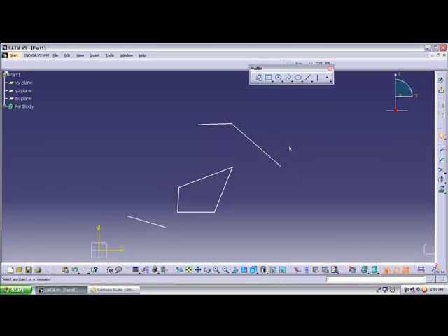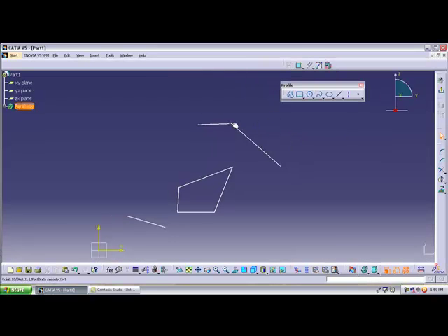So to highlight that icon, we should compulsorily select the profile. Okay, what constraints can you apply for this one? Suppose the line should compulsorily be horizontal, meaning it's parallel to the horizontal axis. Okay, select the object. After that, select the geometrical constraints icon.